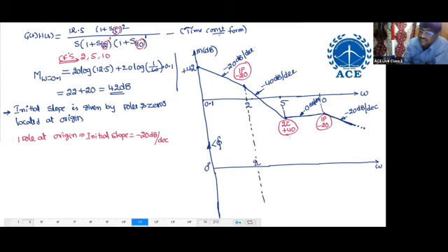This is 2, this is 5, this is 10. Take the projections of corner frequencies 2, 5, 10. Now listen. Actually, to draw the phase plot, we have the phase expression written here.